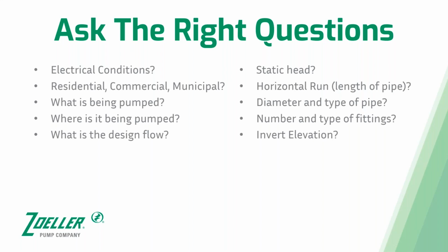You need to know where exactly it's being pumped to. So are you pumping to a septic tank? Are you pumping to a gravity system? Or are you pumping to some sort of pressurized system that your pump needs to be able to overcome?